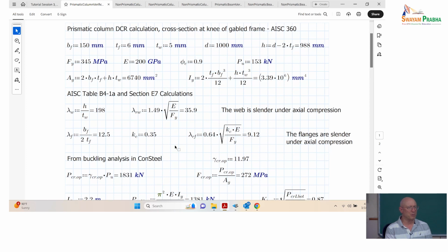In the Eurocode, we say, okay, I want to check my effective widths of my class 4 plate at yield. So I get an effective width based on yield. Then we have a cross-section resistance. Once we have a cross-section resistance, then we have a chi factor that reduces the cross-section strength based on whatever column curve is appropriate for the section we're looking at, right?